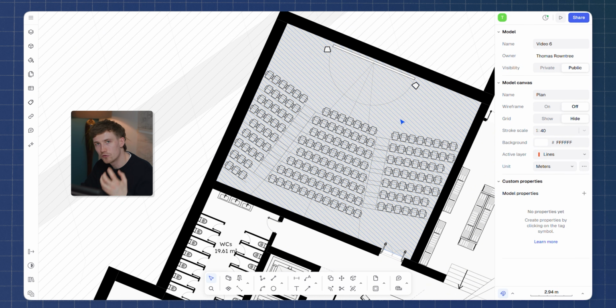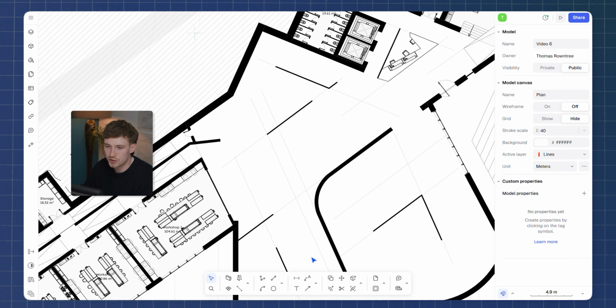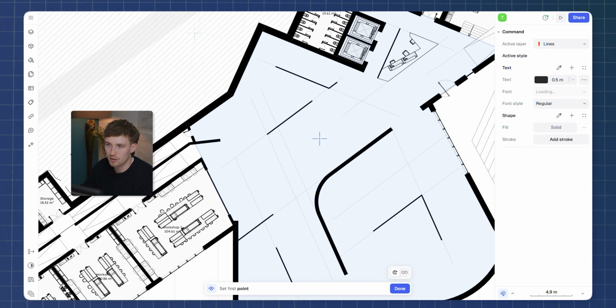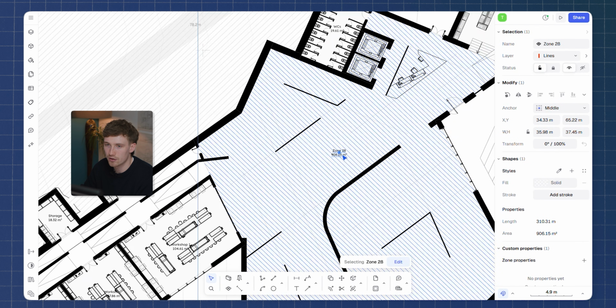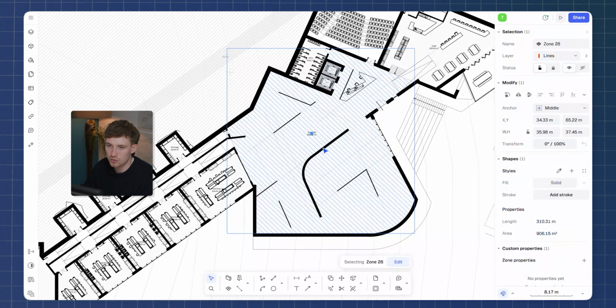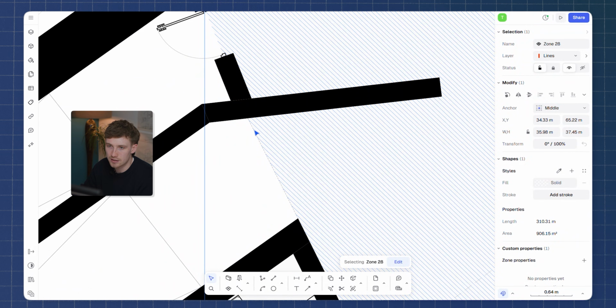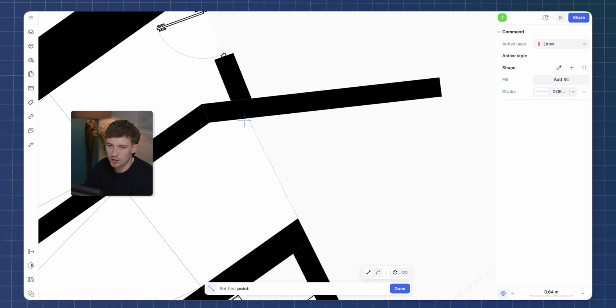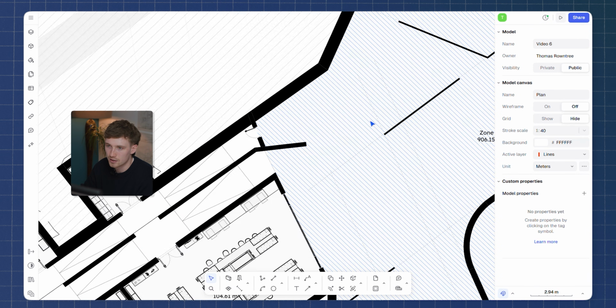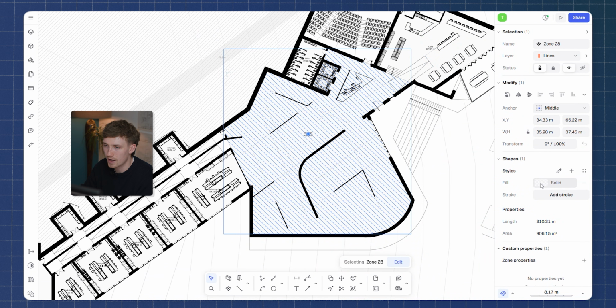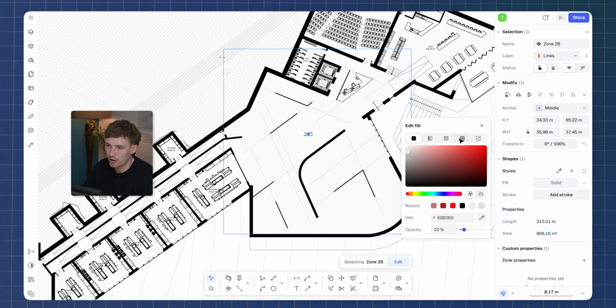Now, because of the tone of the drawing and the architectural quality that I want to show, a kind of analog and sketchy feel, and we want to make sure that we communicate that through this drawing, I'm actually instead just going to add some hatches to these drawings. Another alternative way of doing that is you can select your zone and apply a zone to a certain area which is enclosed by certain walls. And if it isn't, you can see here that this is a zone divider that is creating that separation for that zone. If we select this element, we can also apply a hatch to this. So we're going to apply a hatch.